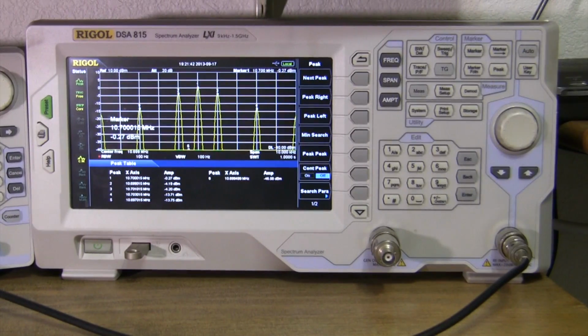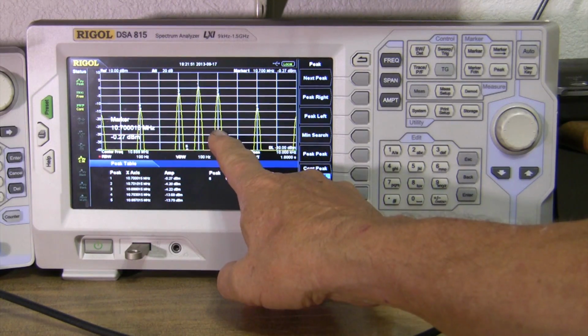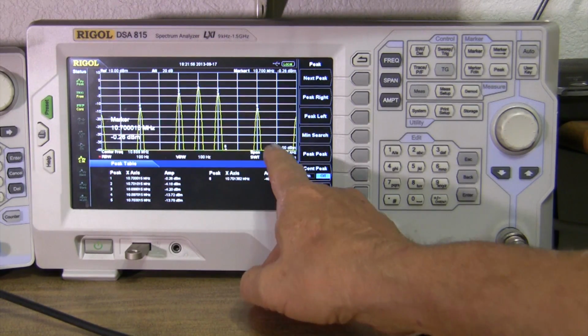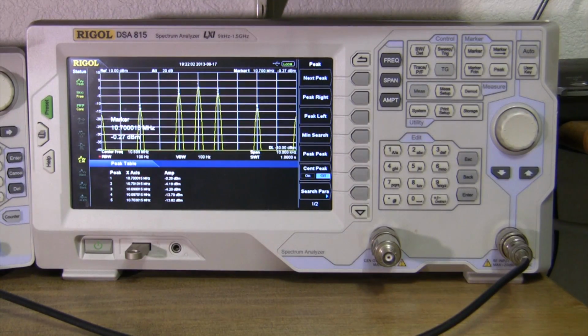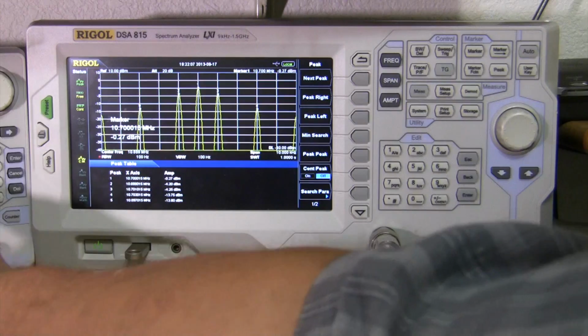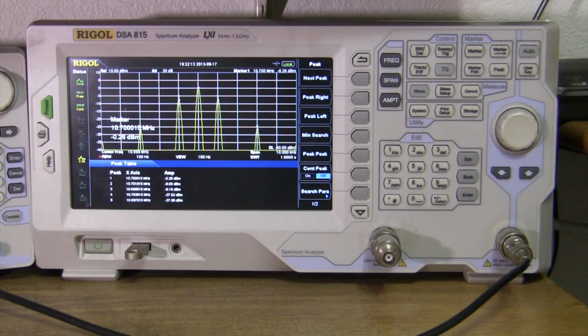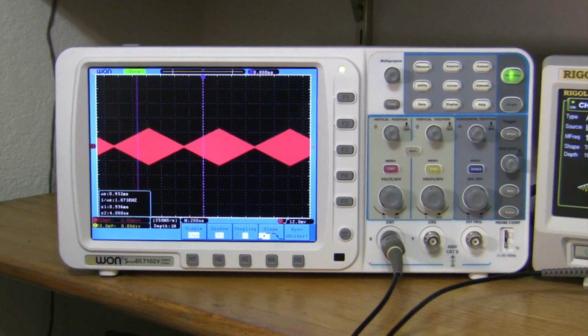And you'd expect it to splatter all over the place like it does. Notice that the third is way down. Here's the first harmonic, if you wish. The second is suppressed. The third's there. The fourth is suppressed, and the fifth is up here. So that's what we'd expect out of a square wave. All right, let's go to shape, triangle. Yeah, once again, they've got the same kind of triangle waveform there, but with carrier in this case. Come back over here, still looks like a triangle.